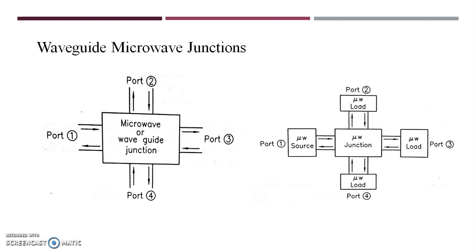We have studied the maximum power transfer theorem. If the load is connected with the characteristic impedance, there is no reflected wave. Maximum power transfer will take place and no reflected power will be there. If there is a mismatch of the load other than the characteristic impedance, the reflected power will be there, and the combination of the incident and the reflected power will give the standing wave pattern. And these scattering parameters are studied using the standing wave patterns.